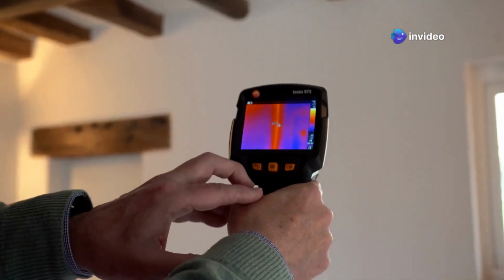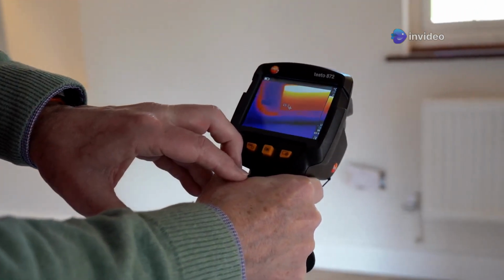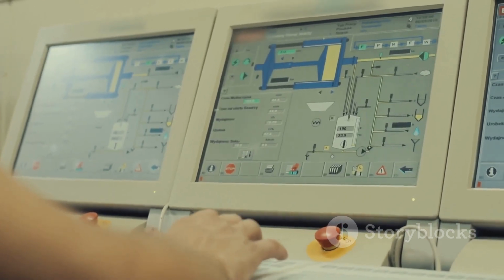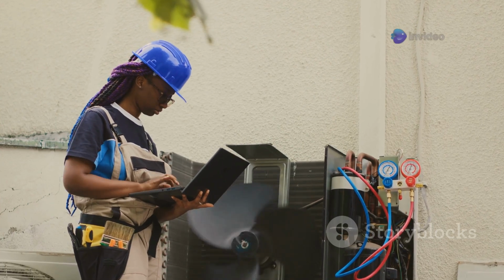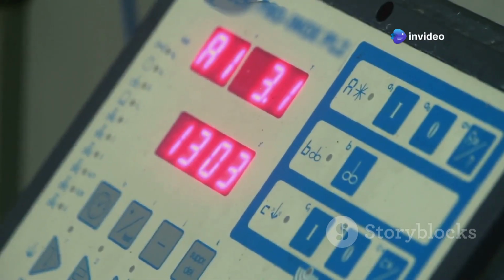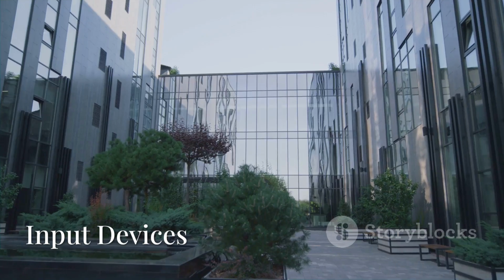This is far more precise than a digital signal which might only say too hot or too cold. This precision allows the building automation system to make much finer adjustments. It helps in maintaining a very stable and comfortable environment for occupants. These versatile signals can represent any value within a continuous range.